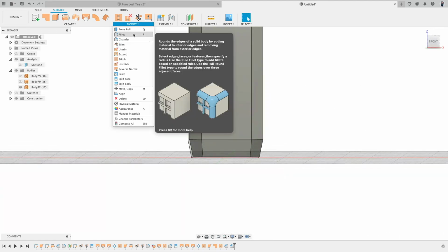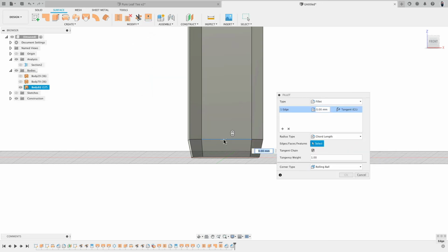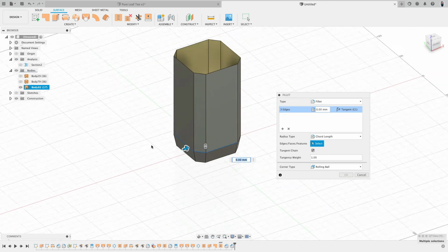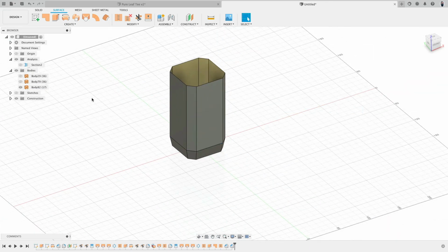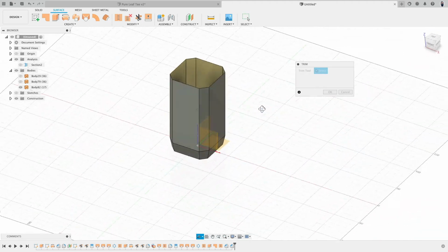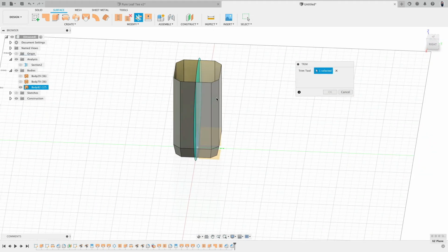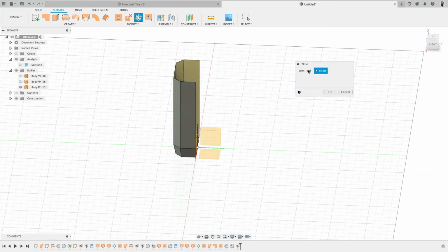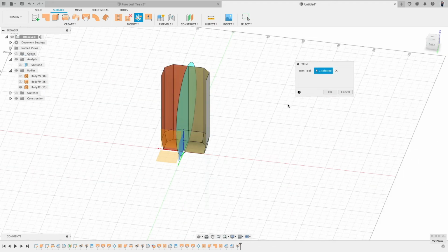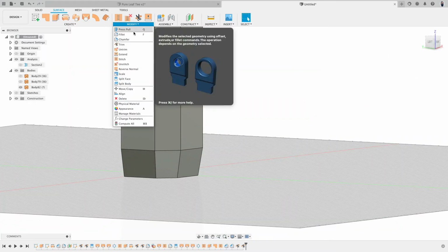These edges we would like now to round, so we go fillet. And yeah, chord is fine. And I will actually, no. So this is now the point where I go back into my trimming. Why do I do the trimming and not filleting all? Filleting is a complicated task. And by removing literally 3/4 of material I don't need, I save the software a lot of work.